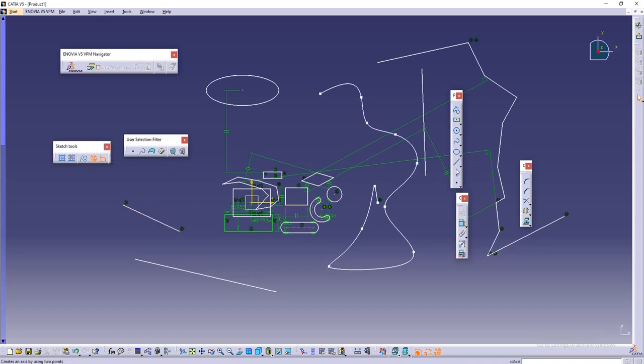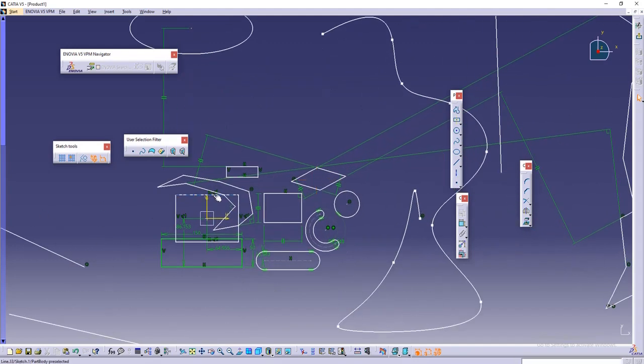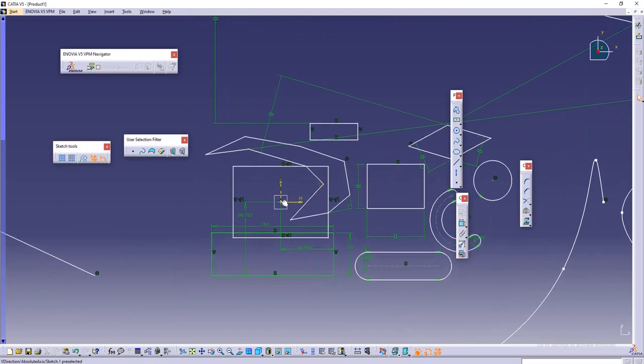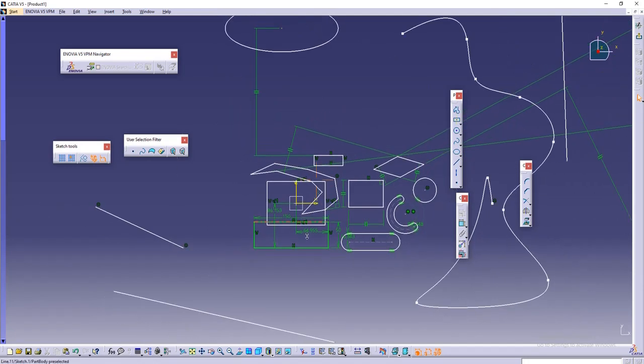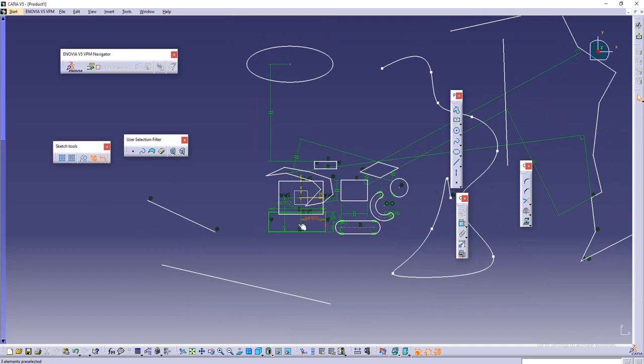Then there is the axis, which is mostly used in CATIA for your references, because I have already told you initially that it is very important in the drawing phase. You have to create the constraints, right? You have to constrain with the x and y axis, and if it is difficult to constrain from this, you definitely need some axis, some guides where you can say okay, this distance is from this axis and that axis, right? So you need to create some reference lines, center lines and axes. This kind of axis you can create with this.